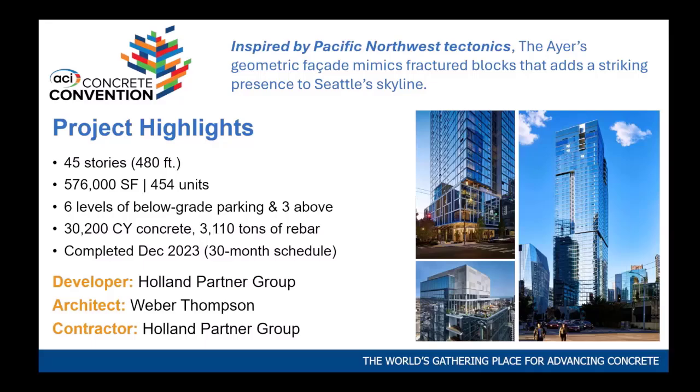If you look at the building, the way it's been designed, it was inspired by the Pacific Northwest, where you have these jagged sides. This is actually the tectonic plates, quote unquote, per the architect, that shows that facade that goes in and out, which created some challenges for us from a structural standpoint, because we had to create these long cantilevers without moving columns.